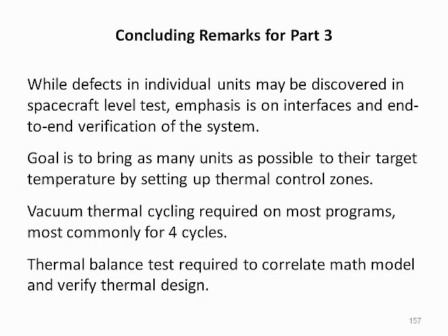In our discussion of spacecraft-level thermal testing, we have learned that while defects in individual units may be discovered in spacecraft-level tests, the emphasis is on interfaces and end-to-end verification of the system. During the test, the goal of bringing as many units as possible to their target temperature is accomplished by setting up a number of thermal control zones within the spacecraft that can be independently driven to different temperature levels. We also learned that vacuum thermal cycling is required on most programs, most commonly for 4 thermal cycles, and that thermal balance testing is required to correlate the thermal math model and verify the thermal design.